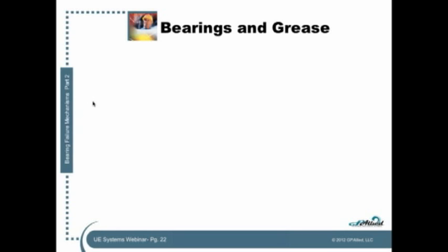But in those environments, there are people spending time and money and research efforts trying to derive some type of prognostics algorithm whereby they can collect certain pieces of information from the machine, certain vibration characteristics, and run it through this algorithm and determine how many days are left. So there are some rare instances where that is being researched and progress is being made. However, let me give you some of the challenges they're going through.